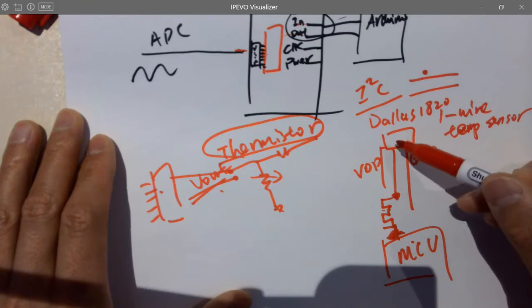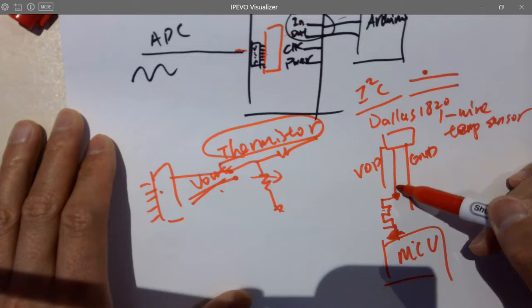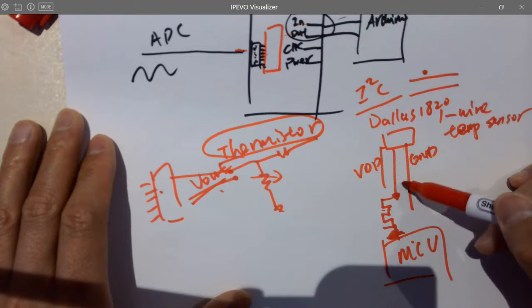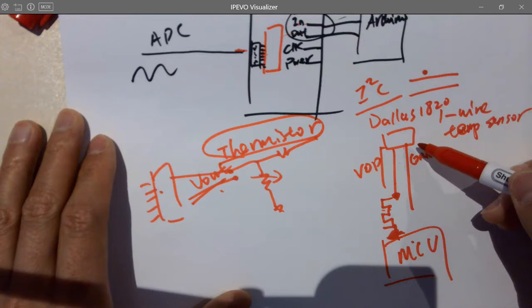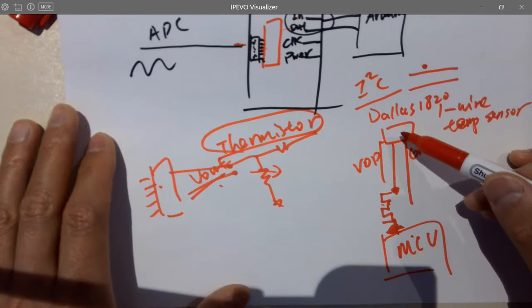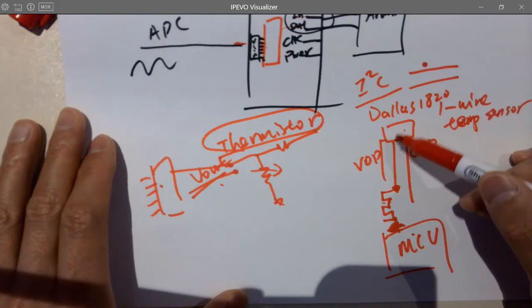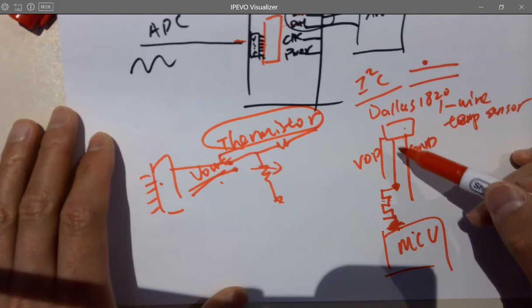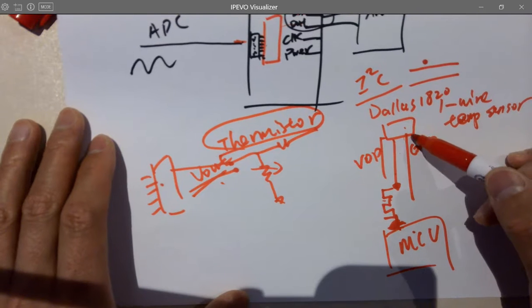There must be a digital block over there to do that job. It is able to send every single bit in serial on just one wire instead of 8 or 10 parallel wires. It just integrates everything inside. You don't have to do all this digital analog conversion and also the parallel to serial conversion by yourself. So that's what's happening for this temperature sensor.